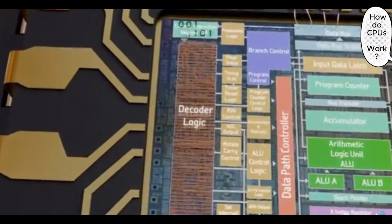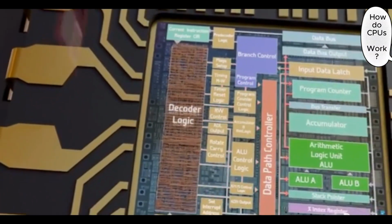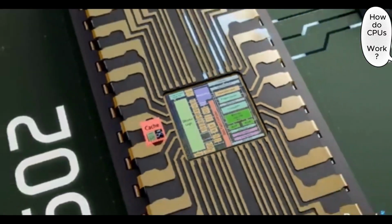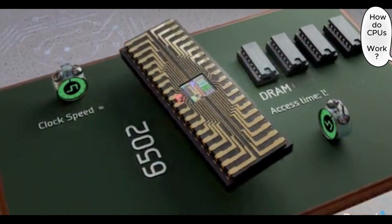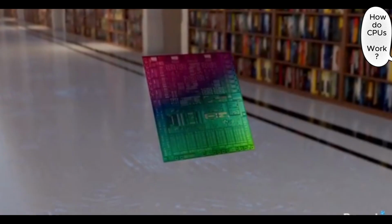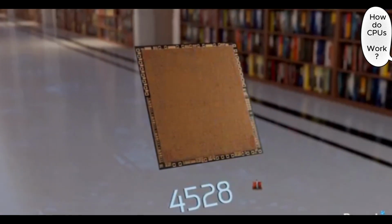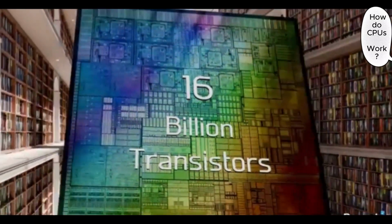Finally, here's where the instructions are decoded and the control signals are generated. One note is that there's no cache in the 6502 because the DRAM chips in the 80s were just as fast as the instructions, so the table in the analogy is even smaller. As we said at the beginning of this video, the 6502 chip is made from 4,528 transistors. So let's see what an M1 chip with 16 billion transistors would look like.